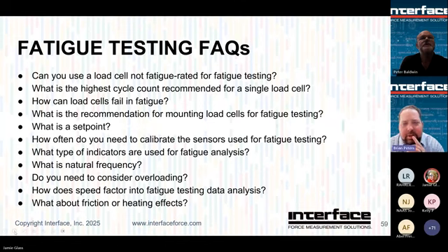How often do you need to calibrate the sensors used for fatigue testing? Well, I'll go ahead and answer this one. Sensor calibration in general, it's kind of up to the customers. We recommend annually to start. After that, if you've got good confidence, fine. Now, fatigue testing is a little bit different. If you're going to be performing fatigue testing, best practice would be to have sensors calibrated before a big test, run the test, and then have them calibrated again. That'll bookend your data, give you high confidence that what you ran and the data you collected was just as good at the end as it was when it started. So that's what we recommend there. And that there was no damage to the sensor.